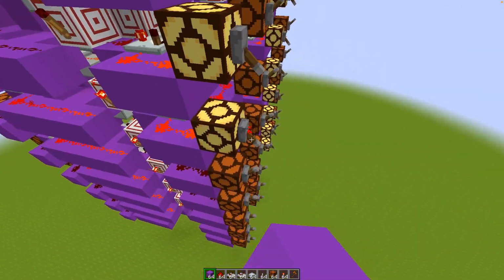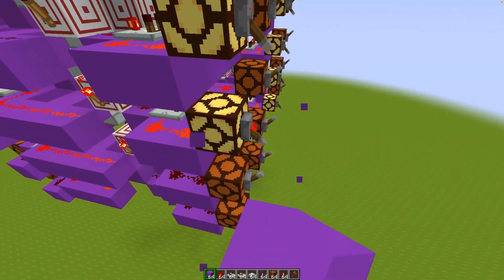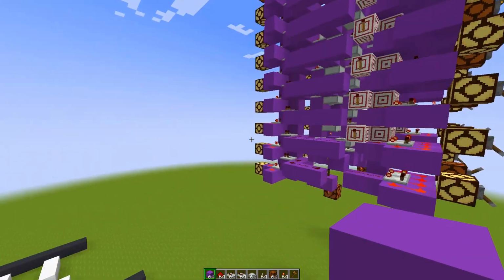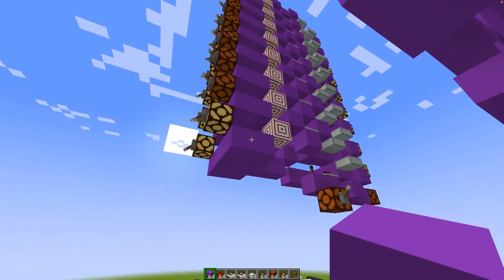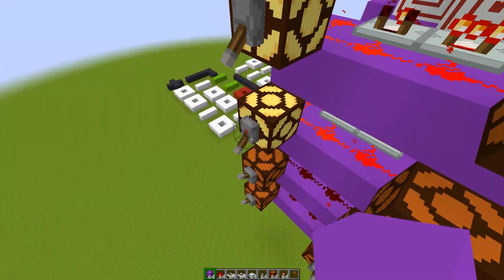So let's put in 255, which is just all the bits, because it's 8 bits. There we go. And then let's turn on the carry. There you go, it works. And this works as well. Great. So that's our carry cancel adder.